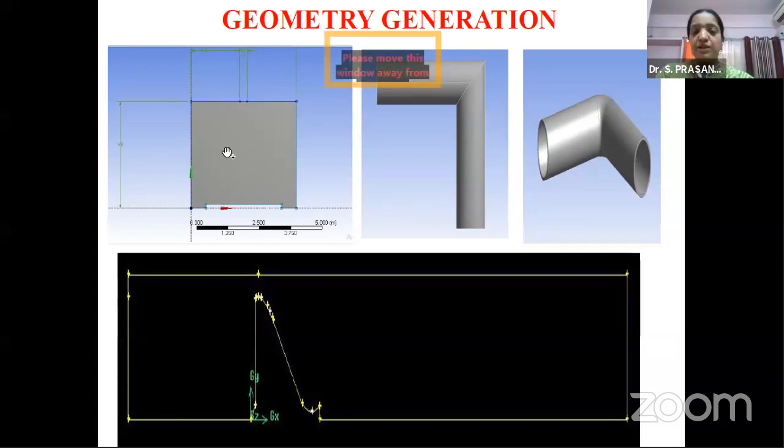These three figures which I'm showing on the top, like your square section, show the flow taking place over a distribution chamber in 2D. This is a pipe analysis which we have carried out for the regular and for the round curved version. So these three geometries are exclusively created in ANSYS Workbench. ANSYS gives you a module called Design Modeler. Once you click on Geometry, it will open a window called Design Modeler.